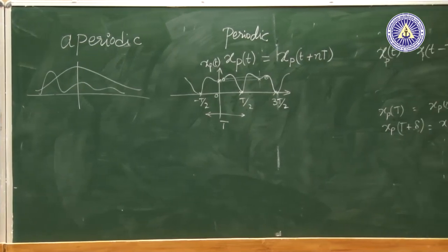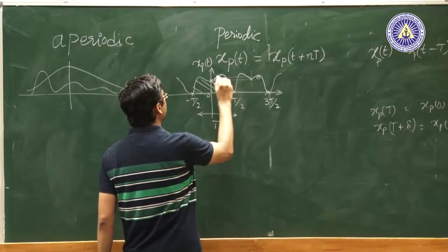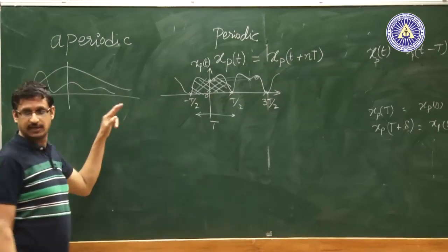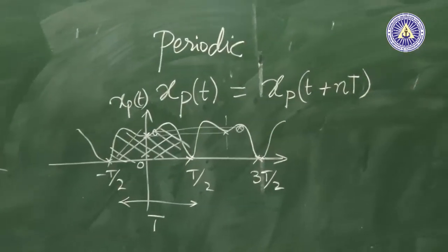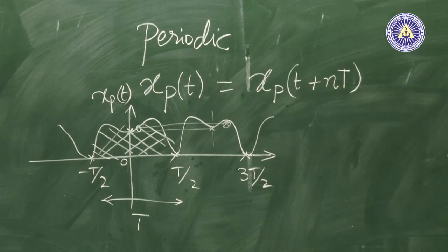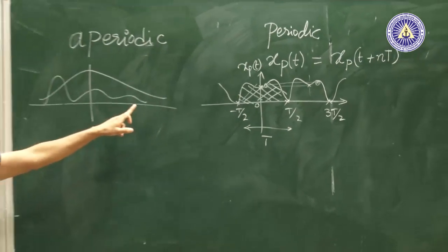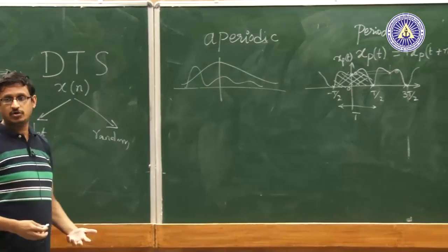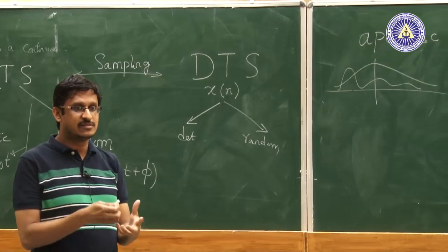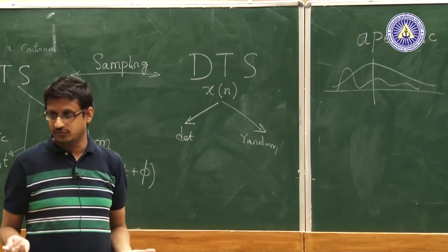Why you can say that one? Because you have actually seen that this fundamental period, if I were to shade this area, you can actually see that this area has been repeated by translating the signals by capital T units, right. You can actually see this, there is no problem with that. So, it is very easy to spot a periodic signal when it has been properly plotted for you, okay. And you would say the same thing here, right. But in many cases you would not be able to plot a signal and then check and then determine that this signal is a periodic signal. If it is a periodic signal, what would be its period, and so on and so forth, okay.